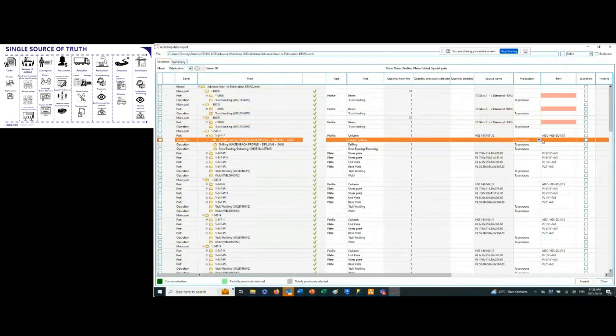Also, at this level, you could choose to subcontract different assemblies or choose not to produce them altogether. So if, for example, you're a fabricator and you've been allocated a specific part of the fabrication process, but you're receiving a model from a detailing firm and they consolidated everything to optimize holes. So, for example, they could have a special part from Advanced Steel coming in as well, which are typically mechanical components, 3D solid shapes, just to use as reference to apply holes on beams and so on. You could choose to ignore those items and not import them into your order, ignore them altogether.